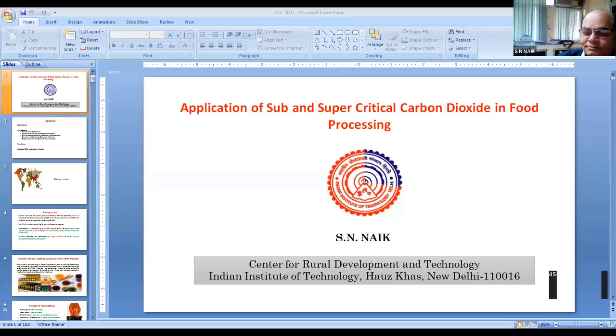We have filed a patent on that against the Brazilian process. In Brazil, for turmeric, they have used supercritical carbon dioxide and ethanol. It requires 350 bar or so. Above 300, you are getting the curcumin. But if you use a solvent under high pressure, time will be reduced and your solvent consumption is reduced to 1/10. So it is economically viable to remove solvent, and the energy cost as well. You don't even require very high pressure, and plant cost will also reduce in the process.